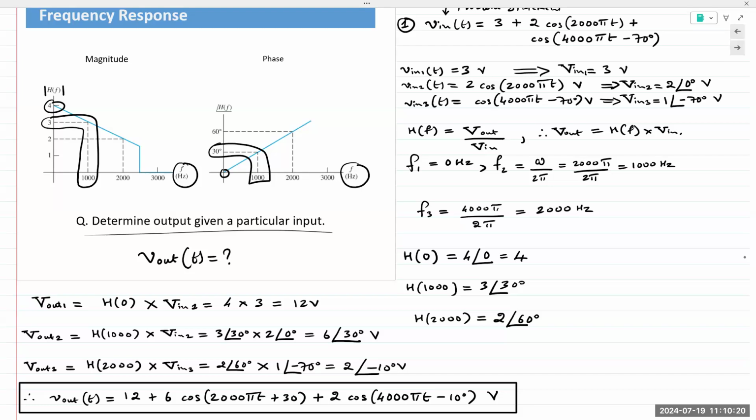And when it comes to wireless signals, especially, as soon as they transfer out from the transmitter, they get weak because loss occurs when it's transferred through the air. So by the time the wireless signal does reach our receivers, the signal is very, very weak. So in addition to filtering, we also have a small amplifying section at the front. It's also known as the preamplifier. It'll take the relatively weak signal and impart some strength to it.